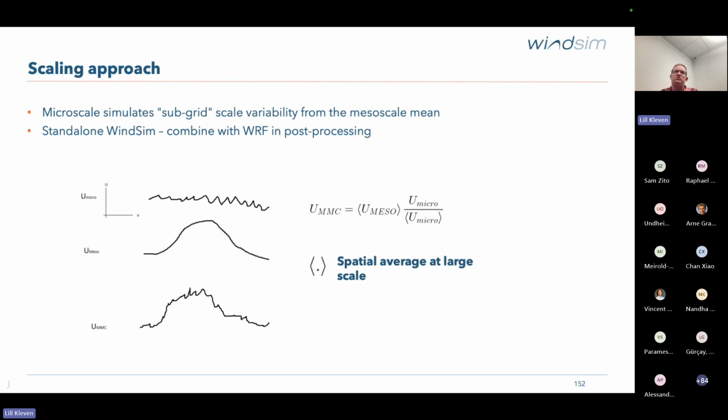But because the terrain and the roughnesses can be very different at the resolution of the mesoscale model and the microscale model, if you have the mesoscale virtual climatology at some kind of a hill that is not represented inside the mesoscale model, or in a valley, then you get very different and inaccurate predictions for the wind resource using that naive virtual metmast approach.